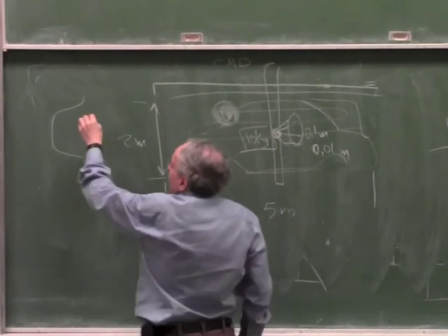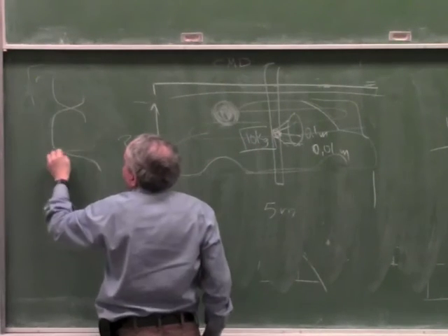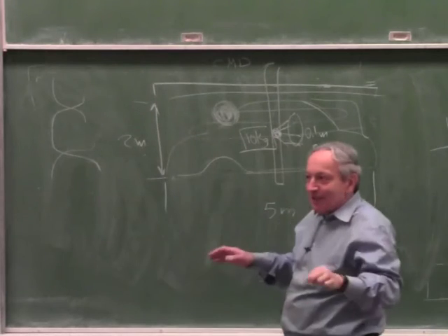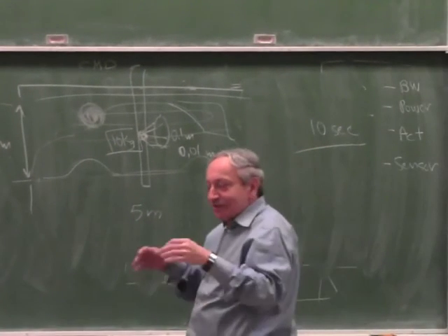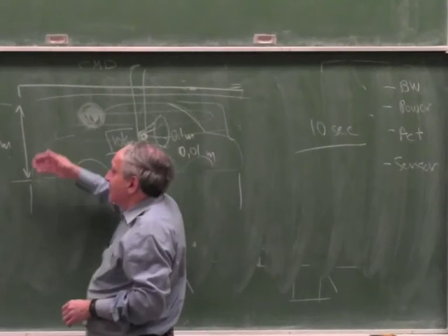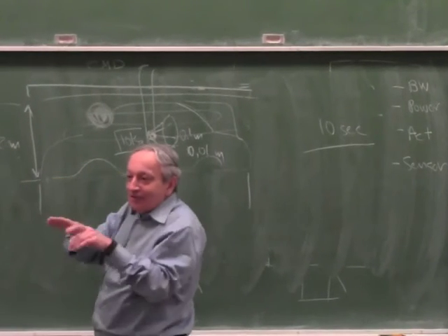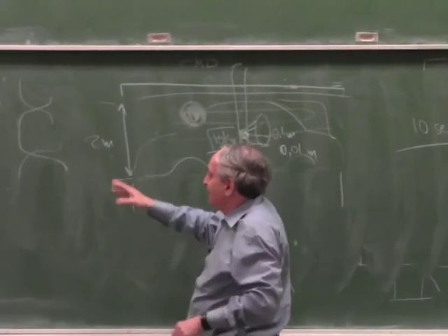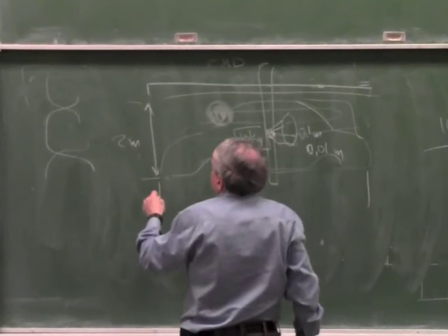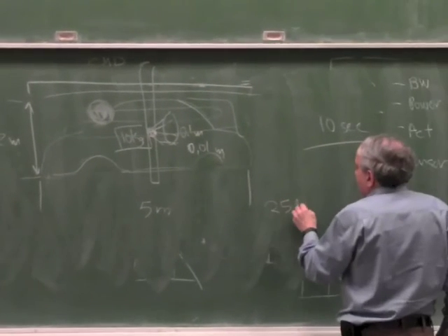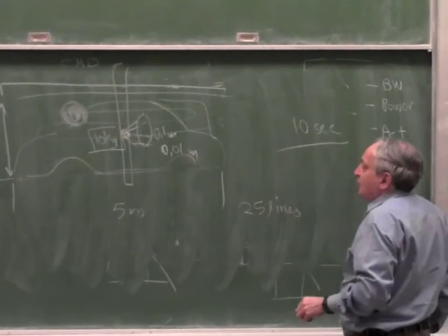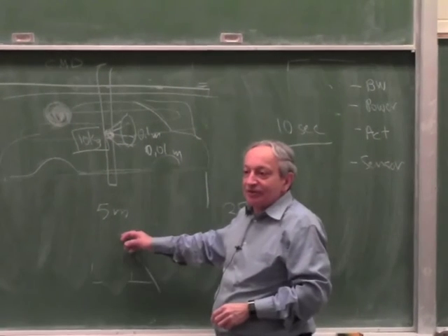So probably you want to have some overlap just to get nice painting. If you really were designing it, not just for the exam, you'd have said the minimum is 20, but it's very bad to leave a gap between scans, so let's make it 25. So you have 25 scan lines, and each line is 5 meters long.